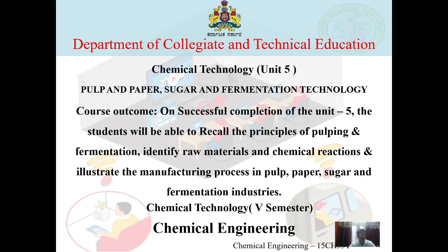The pulp from the blow tank is passed through a series of screens to remove the knots and lumps of fibers, centrifuged to remove foreign material, then concentrated in thickeners and sent to the bleaching unit. The bleaching is carried out to remove the color bodies from the pulp, and this pulp consists of around 80 to 90% dry fibers.